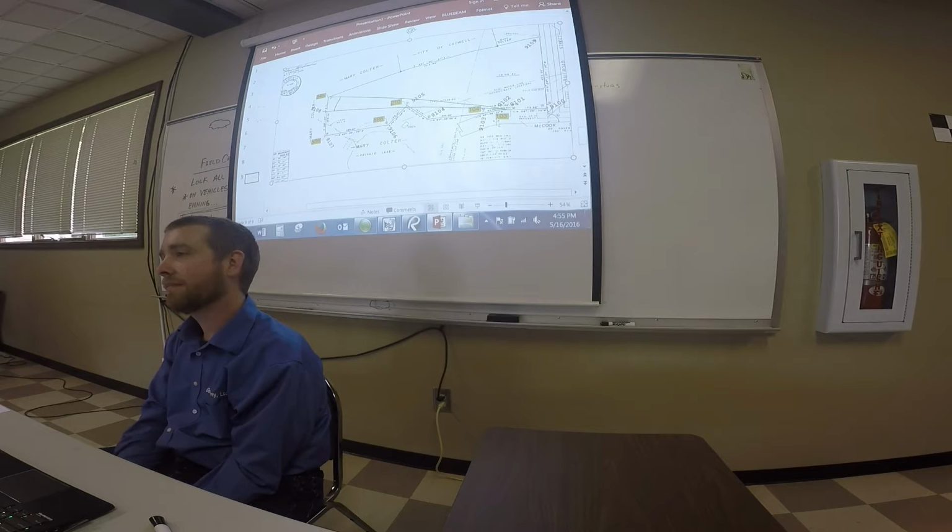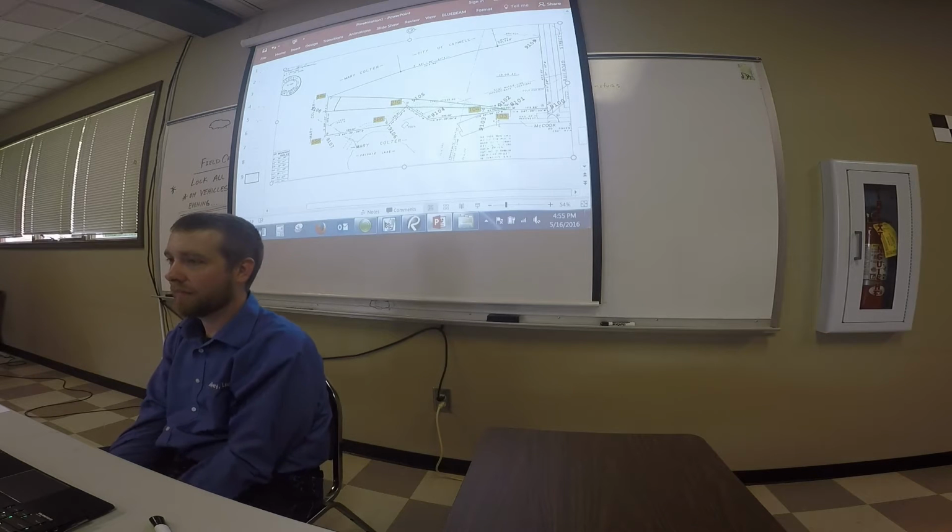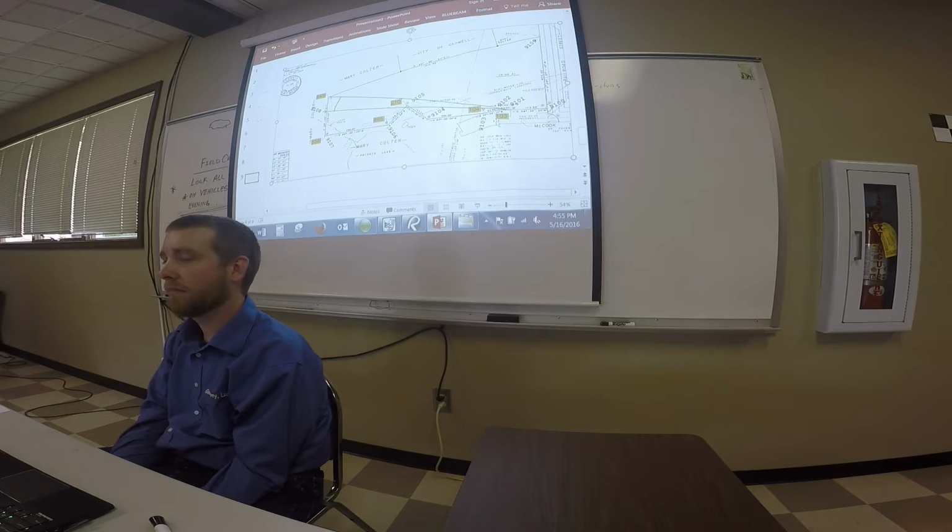Okay, so we got a real-time example. Tim, I don't want to make an example out of it, but I am, because we had an opportunity last week. Residential West Cobb pasture, one missing pin, back corner. It's been pretty easy now that you've got these tools we've just given you. You could have taken that flat, turned that angle, calculated those coordinates, and likely with a phone call, you could have said to the PM, hey, here's what I got.